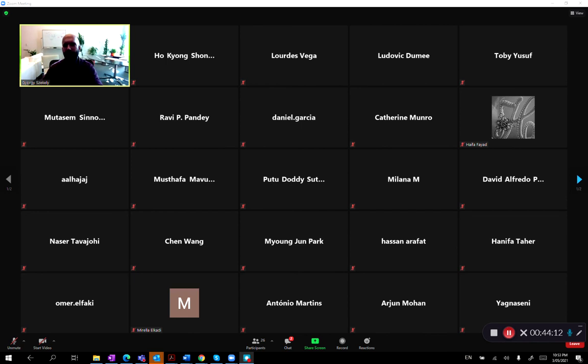The applications that I know of include solvent recovery and catalyst recovery. These are the main applications nowadays, but also biofuels. The application of OSN in biofuel purification and separation is also emerging. And there is some interest from petrochemical industries for the pre-treatment of diluents and other types of streams that they have on a large scale.